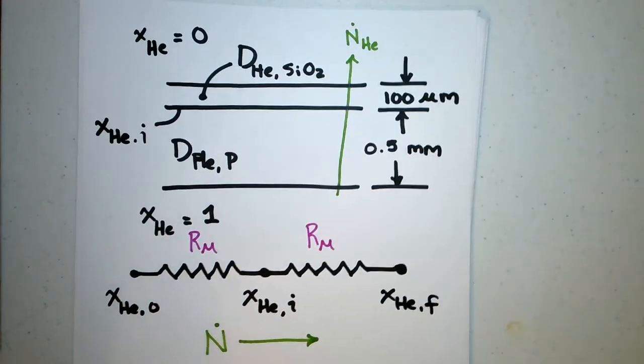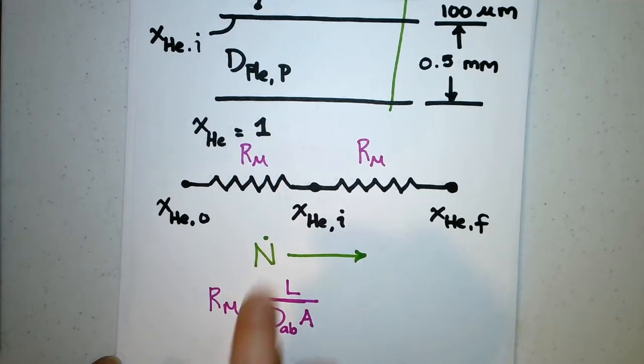So if we apply this to our system here, what we're seeing is this length would actually be the thickness, and the diffusion coefficient would, of course, be whatever the diffusivity is in the material, and that changes by an order of magnitude between Pyrex and silicon dioxide. Silicon dioxide has an order of magnitude higher diffusivity. It's much easier to transport through the SiO2. If you deposit this with a thin film deposition tool, it's going to be amorphous and porous. The diffusivity should be much, much higher through some deposited silicon dioxide than some pure Pyrex.